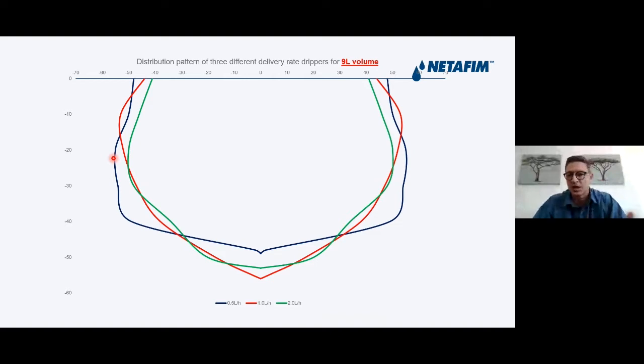Now, if you can imagine, if we put down 2 lines of low flow drip irrigation, which we normally do in an orchard, you can wet a massive area underneath the soil surface without having the losses of an overhead system like micro sprinklers or pivot irrigation or whatever the case may be. We are just applying the water and it's being efficiently used below the soil surface.